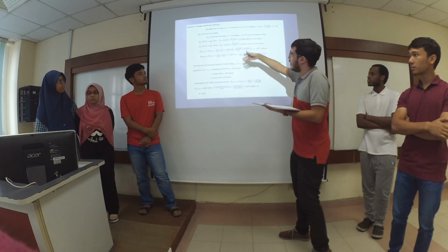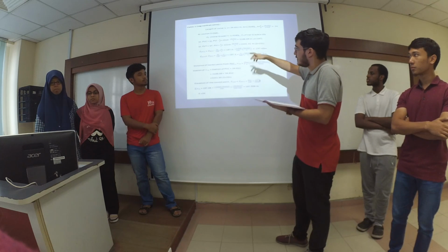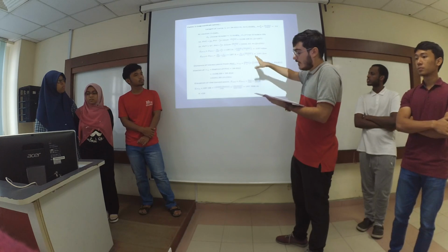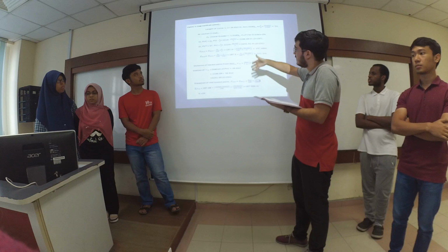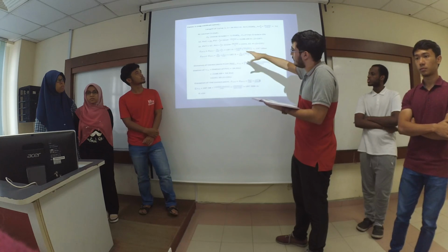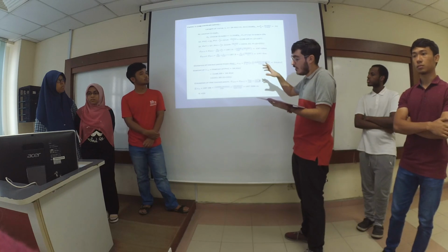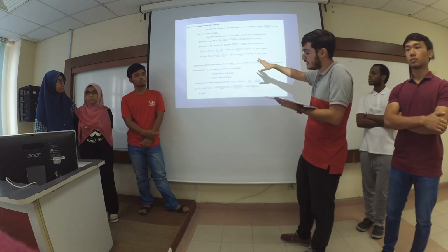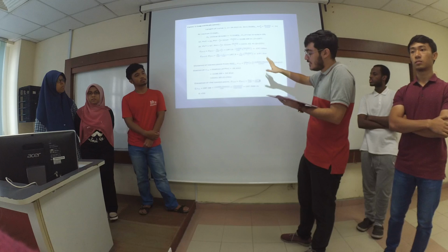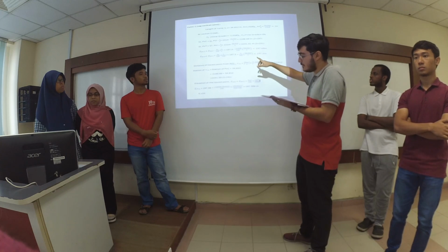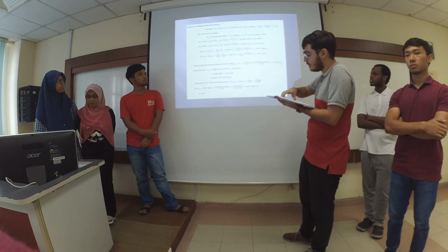This is our calculation for the station of PVC, but before this, it must be mentioned that significant points of the vertical slope, followed by 0% slope, are set as PVI to determine PVC and PVT respectively. This is what we have done in table 3.